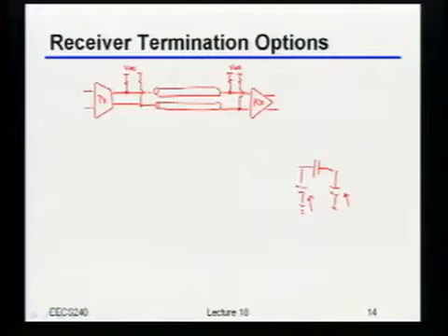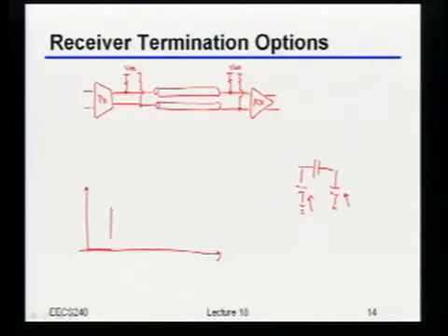Are we assuming that the comparator will compare the highest value, something that you said in the previous lecture? Yeah, so you should assume that, for example, if this was the ideal transmitted bit and your amplifier responds and does something like that, then you can indeed assume that it'll sample at exactly the right time. Now, obviously in a real system that's not exactly going to happen. But for this project, you can find the peak of that voltage and assume that you sampled it exactly at that time. But we might have a signal loss there, and that is a trade-off with power. Exactly.